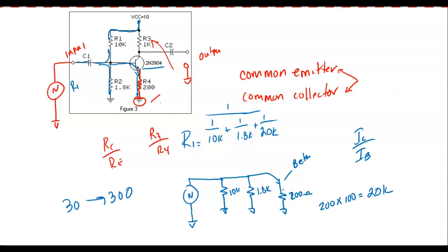So what would be my input resistance to the circuit, RIN? So my AC signal is going to work into a load. And how much current is required by my AC signal determines what load this input of my transistor provides to it.